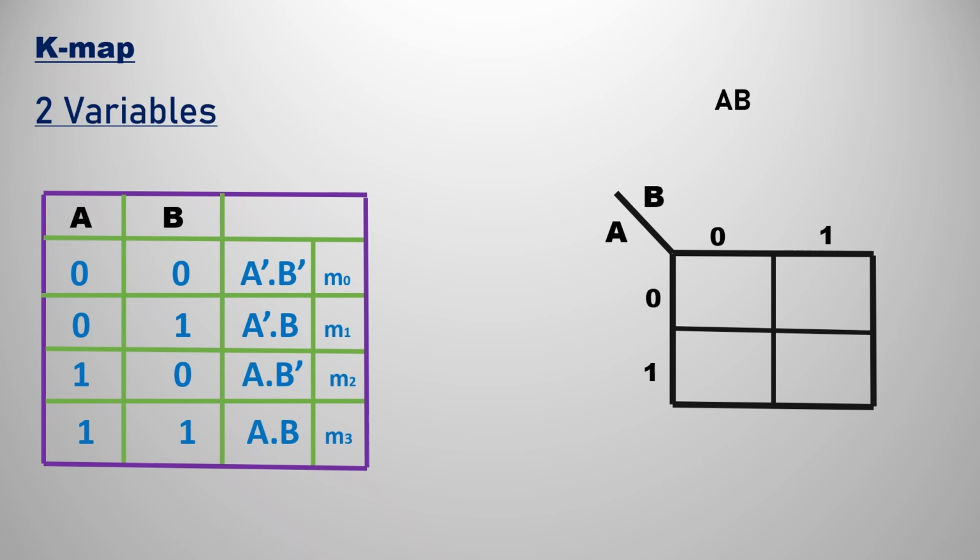So you are going to represent these in the SOP form, sum of products, that is A bar into B bar. So if 0 is there in the place of A, 0 means A bar, and 0 under B is B bar. Suppose the second term, that is 0 1: A under 0 is represented as A bar, and B under 1 is represented as B only, not B bar. That is how you represent all of these in the truth table.